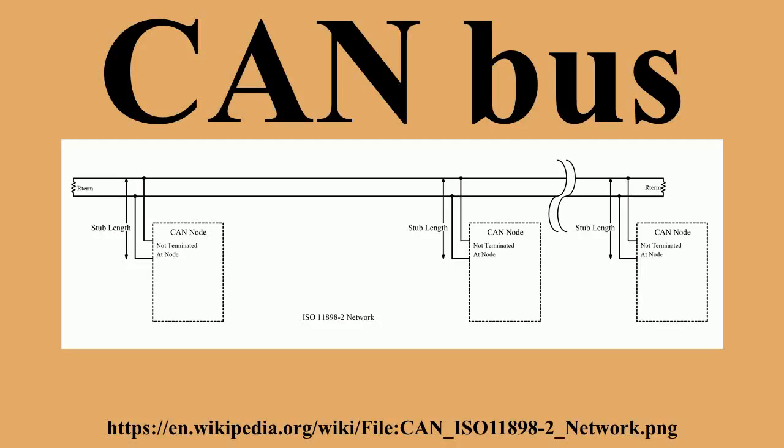Also, in the de facto mechanical configuration mentioned above, a supply rail is included to distribute power to each of the transceiver nodes. The design provides a common supply for all the transceivers. The actual voltage to be applied by the bus and which nodes apply to it are application-specific and not formally specified. Common practice node design provides each node with transceivers which are optically isolated from the node host and derive a 5 volts linearly regulated supply voltage for the transceivers from the universal supply rail provided by the bus.